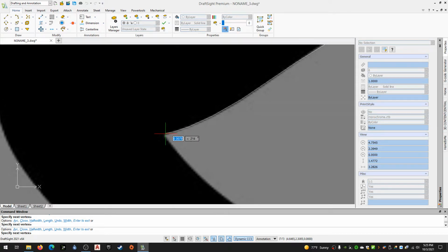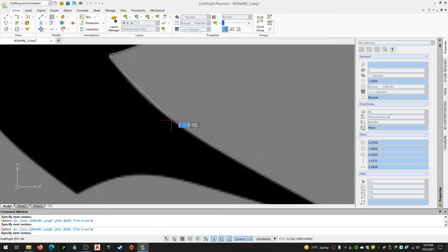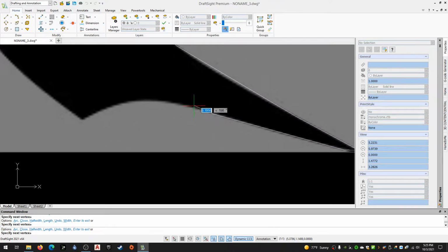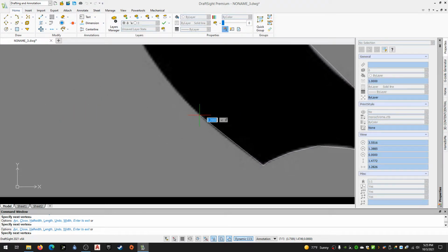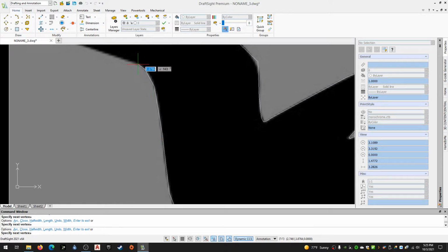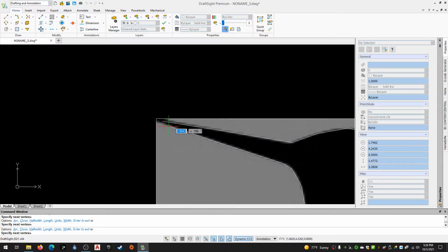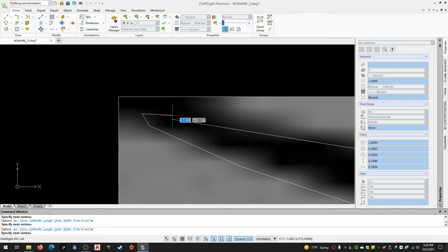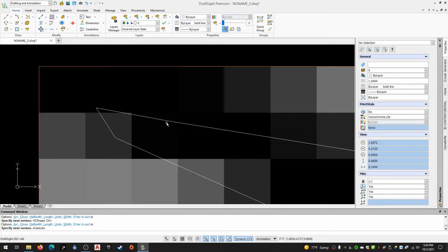So when I get in close here, add a couple extra. Work my way down here, get to this tip, add a couple extra. Same thing here, couple extra on these larger lines or areas. You don't need as many points. And then when I get to this point and I want to end it, I want to make sure that it touches exactly at that point. So I go down here to my snap and I click it to turn it on, and then I can click it, and now if I hit escape and zoom in, I can see they touch exactly.